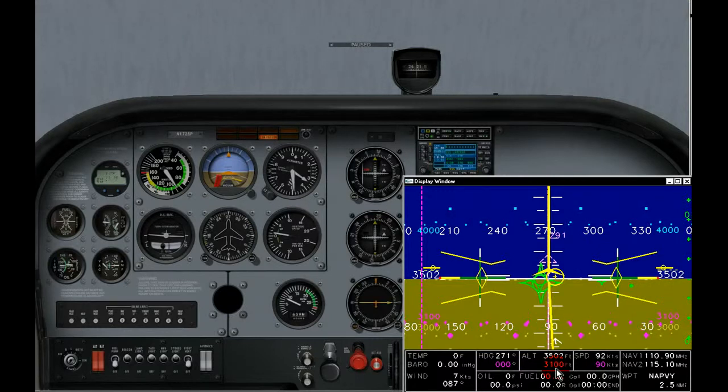Perfect. The next thing I'll do is adjust the target airspeed using the diamonds, and I'll hold down the period or comma key to increase or decrease the diamond. And so here you can see I'm increasing the target value, and it's also displayed over here on the bottom of the screen. So we're going to have 110 knots. And now I'll use the left and right bracket keys to adjust the target heading layer to our first heading, which is approximately 266 degrees. And we want to make sure that it's displayed in green because it would be in front of our aircraft that we're going to. So now everything is set up, and all we have to do is unpause the simulator and execute the flight.